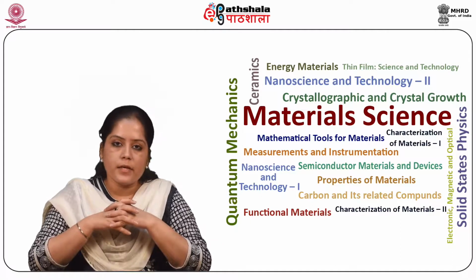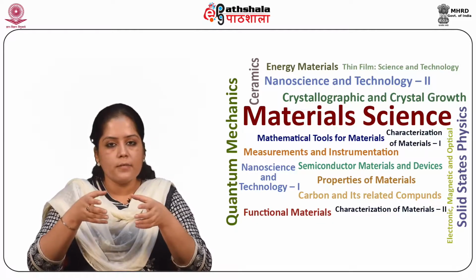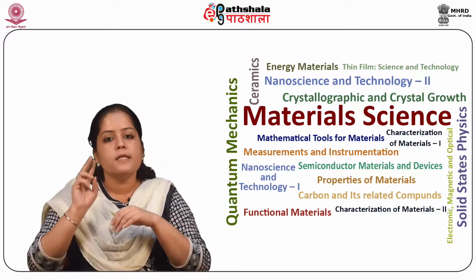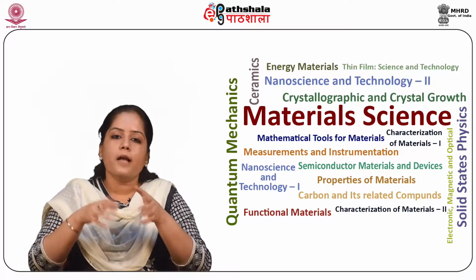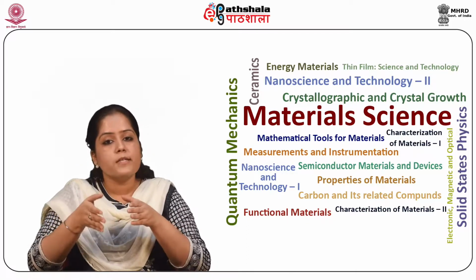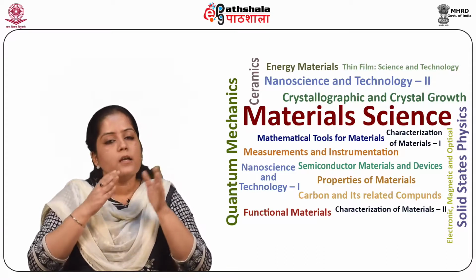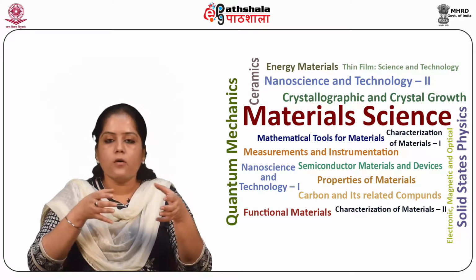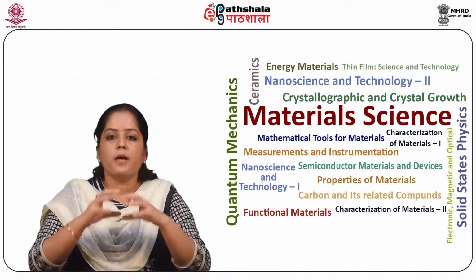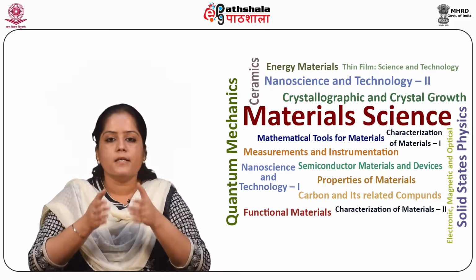So students, let us summarize what we have learnt in this module. First, the toughening mechanisms in ceramics can be categorized broadly into the following categories: first, crack tip interaction, second, crack tip shielding, and third, crack bridging. Next, we discussed that crack tip interactions occur when the crack tip approaches an obstacle such as a second phase particle. The crack can continue to move by bowing between the obstacles, or it may get deflected. In crack bowing, the crack goes around the particles and then joins back again. The particles remain unbroken. Calculations show that this leads to an increase in the fracture toughness.